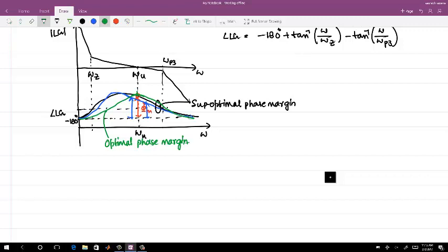right? So the thing is I do not want to change my unity gain frequency, still I want the same unity gain frequency, but I want to place my 0 and poles in such a way that I get the phase characteristics from here. And in addition, whether your ripple suppression will come out to be the same or not, you need to check that. Okay.